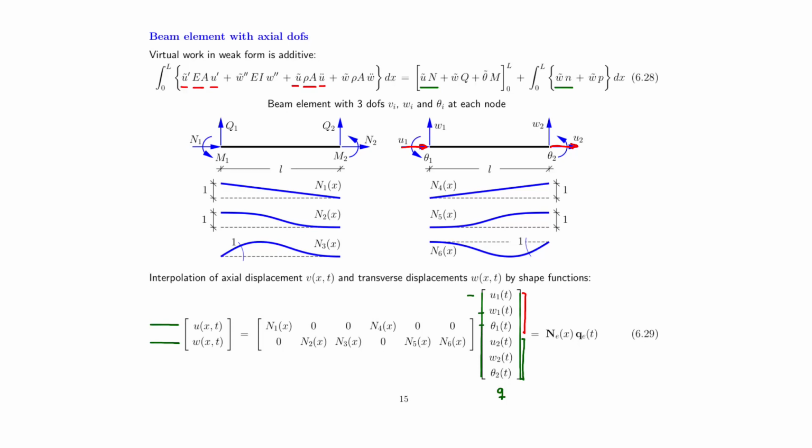And therefore, the four shape functions that we already have considered for the transverse problem are shown at the bottom of this figure here, and they are, in the order of the degrees of freedom, now equal to N2, N3, N5, and N6. And they should be placed at their respective entries, columns, in row number 2 of the interpolation array, and not interpolation vector anymore.